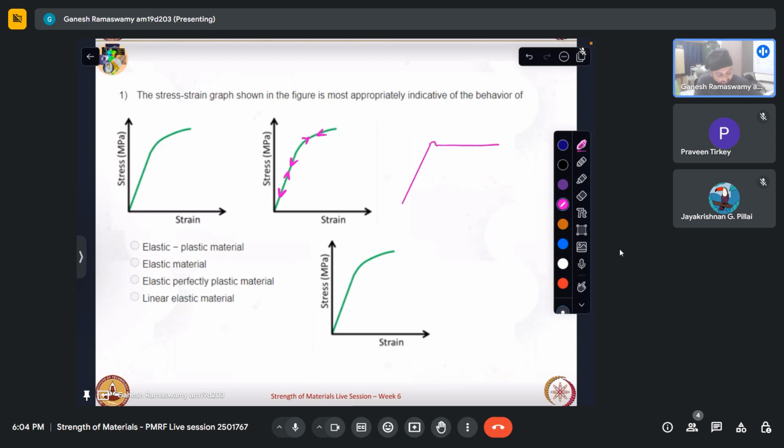So as an engineer we would like to fit this to a curve essentially. So if we do that, let us say that I took this as a straight line and I took this as another straight line with no slope. So what this implies is starting from the load initiation, as I progress, it takes an elastic path.